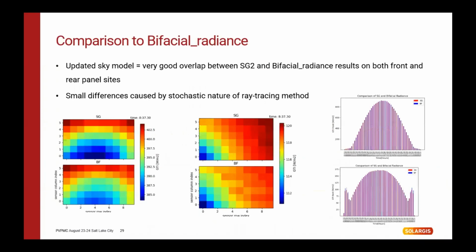When we integrated the anisotropic model, the comparison with bifacial radiance and our simulations were very consistent, for both front-facing and back-facing situations. So it indicates that when we use the same sky model, the ray tracing of our model is very consistent with bifacial radiance.